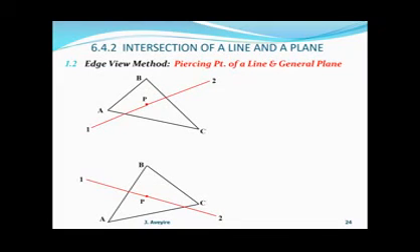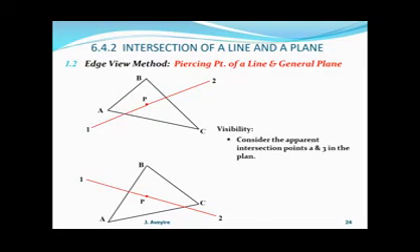Now we consider any apparent point of intersection. So let's take the plan and look at the line 1, 2 and the edge AB. They appear to intersect at this point 3 on 1, 2 and A on AB. Now let us project backward to see what we get. When we project backward, first we meet the line.